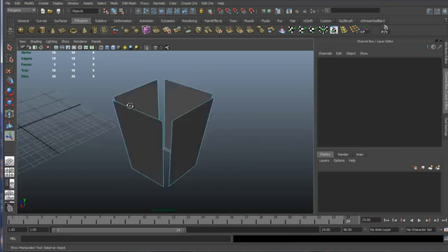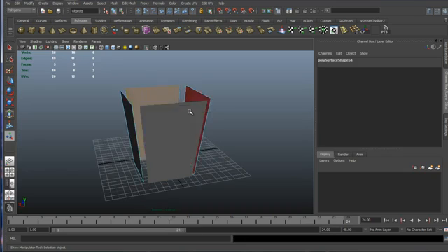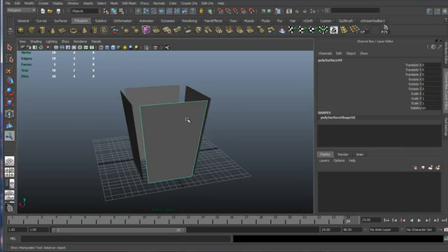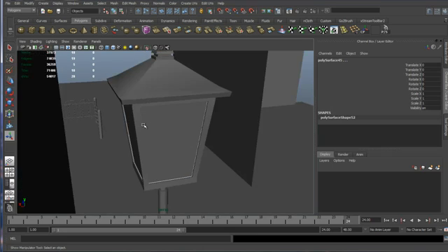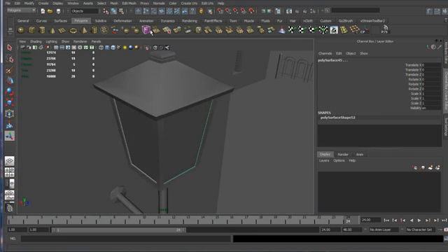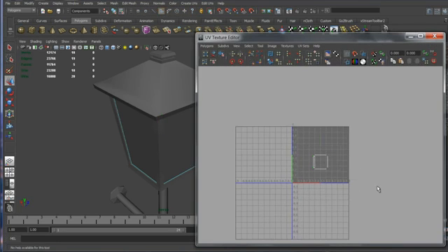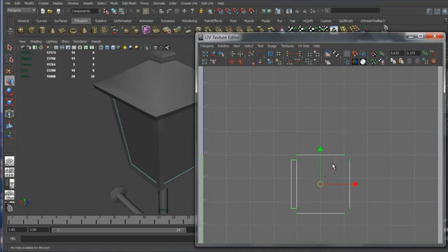And the whole surface area is not big enough, so we don't have the need to UV it correctly. And most of this stuff will be a plain material, just with a simple metal texture on top of it. So now I've removed all the faces of the glass of the lamp, and I'm going to unfold the UVs of those.